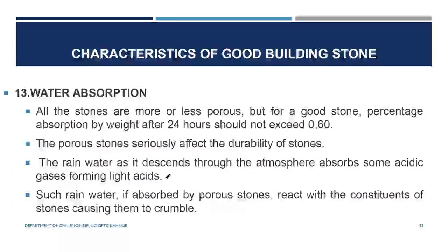Water absorption. All the stones are more or less porous, but for a good stone, the percentage absorption by weight after 24 hours should not exceed 0.60. That is after 24 hours. If you take the stone, put it in the water yesterday and you are testing today, that means after 24 hours the percentage absorption by weight should not exceed 0.60.